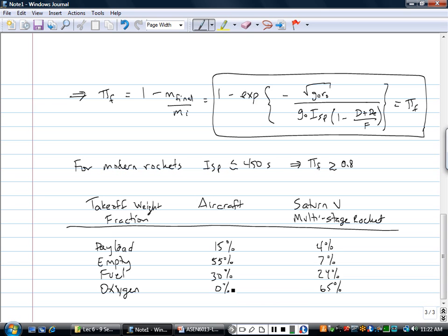So this is not necessarily a good comparison because this aircraft is not going to space, but there's this one thing that we always say when we're pushing why air breathers have an important role to play: when the technology actually gets there and you can get rid of oxygen, 65%, that's a huge weight savings. If you get rid of that oxygen and only need maybe a little bit for the final push into space, or to push for takeoff, or anywhere you need high thrust, that's the benefit. Now, of course, the technology is not there to do this with air breathing engines yet, but as we keep mentioning, we're inching closer and closer every day after 50 years of development.